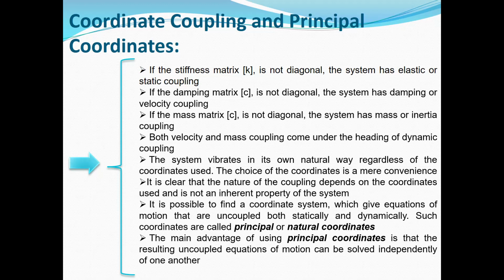Here in 2 degree of freedom systems, when you deal with forced vibration, sometimes it's very complicated to obtain the analytical response when the coordinates are coupled. But by using the natural coordinates, we can convert it into two independent equations.